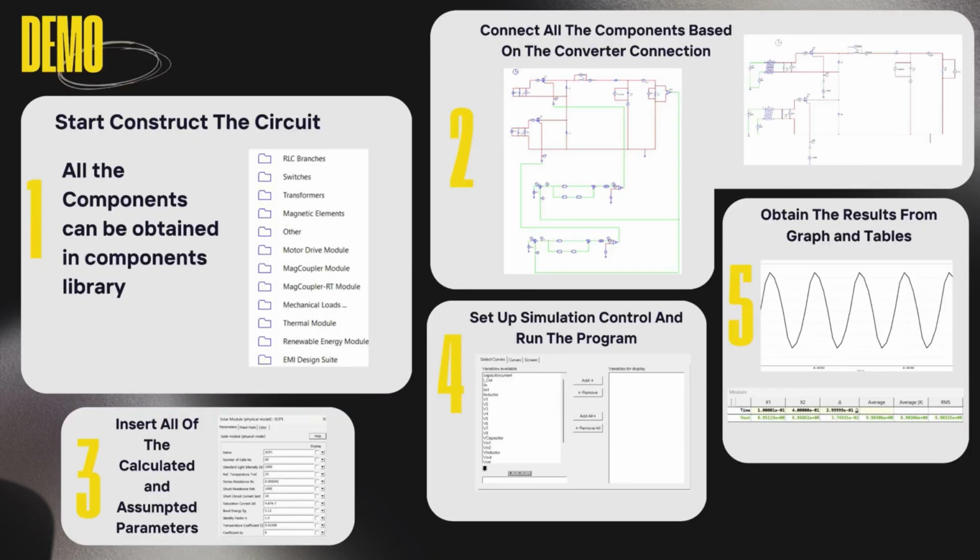So for the demo, we will start with construct the circuit. All the components can be obtained in the components library. The second one, connect all the components based on the converter connection. Here are two circuits of open loop and also closed loop. The third one is insert all of the calculated and assumed parameters. The fourth one is set up the simulation control and run the program. The last one is obtain the result from the graph and also tables.